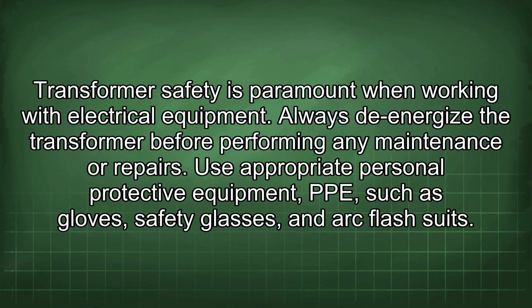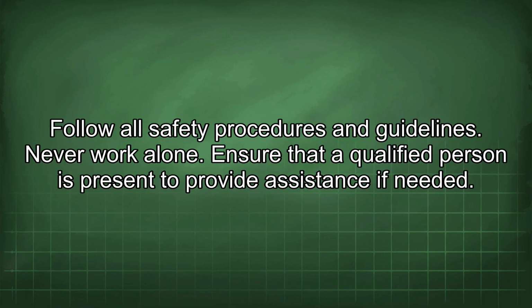Transformer safety is paramount when working with electrical equipment. Always de-energize the transformer before performing any maintenance or repairs. Use appropriate personal protective equipment, PPE, such as gloves, safety glasses, and arc flash suits. Follow all safety procedures and guidelines. Never work alone. Ensure that a qualified person is present to provide assistance if needed.